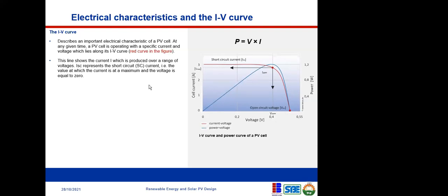For a pump that we use to pump water, the most important variable most times is the head, the capacity to be able to deliver that head. Then the current, which is the flow. Let's say instead of this tank filling in 1 hour, let it fill in 2 hours. Who cares? But the worst case is that it's not able to deliver water at the depth of a borehole. Thank you. Okay, thank you. So I'm glad that we understand this now.